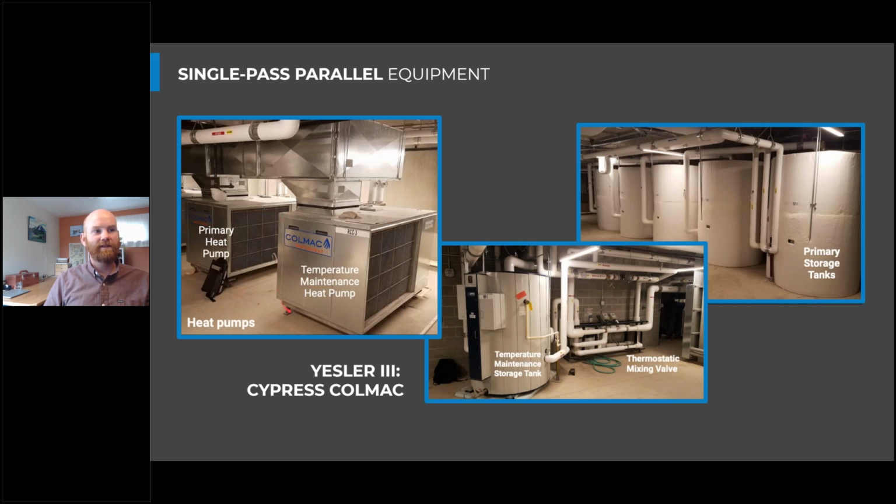This temperature maintenance heat pump water heater isn't controlling to that entering water flow rate. And so we're just trying to dump as much heat into that water as possible. And that water is already fairly warm. So typically high flow rates, entering water and leaving water flow rates, through this multi-pass heat pump water heater with a much lower lift.